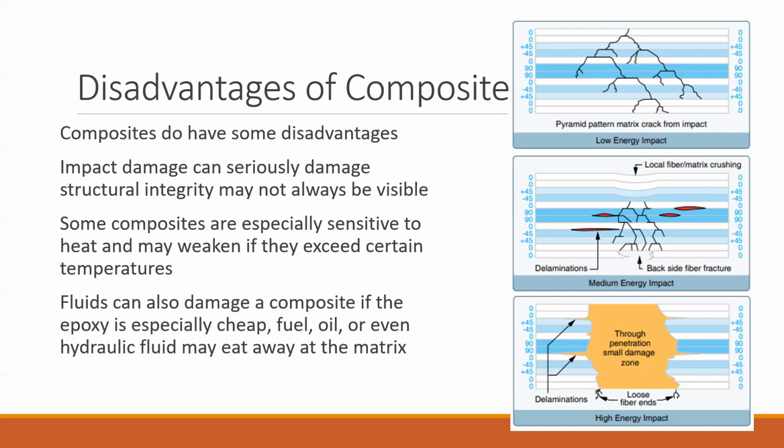Like you can see in these pictures up here, you can see this crack starting to form at the top. You probably wouldn't even know this crack exists, but it's working its way down through the layers, and it's just not good, because over time that could delaminate, especially if fluids like water get down in there and start breaking apart those layers. That could end up very bad. You can end up with your whole wing shearing off or something.